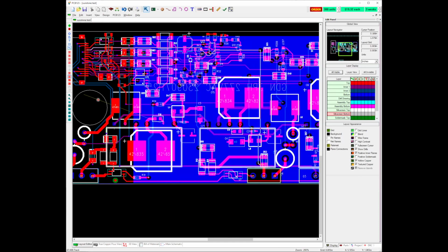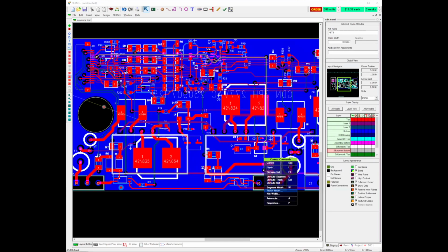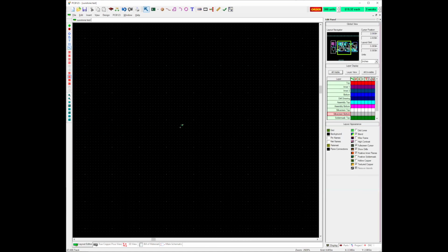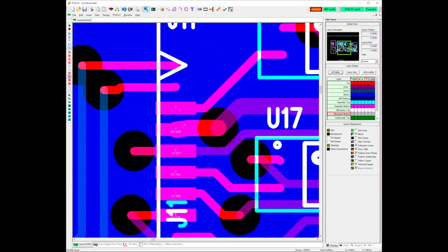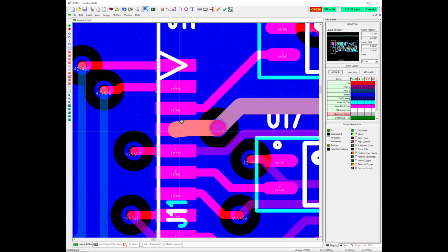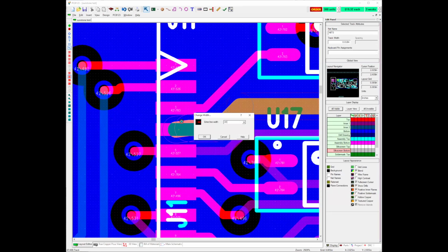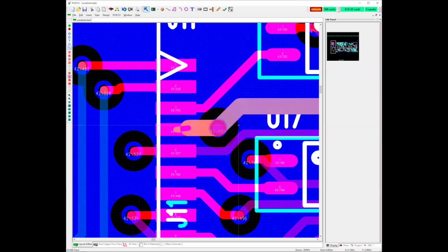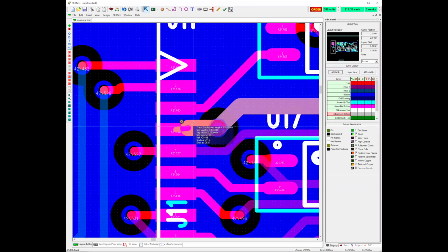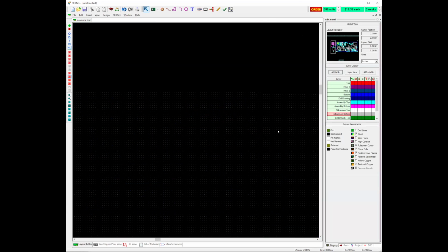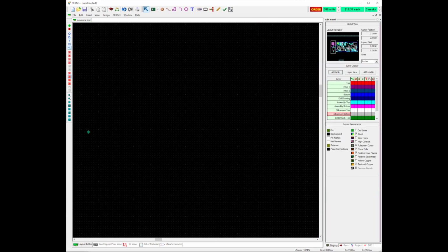It goes up here, changes it to 30 thousandths all the way across the board, but it gives me a violation here, creates an error here, which is fine. I can go back and change that, but I have to follow that whole length of the trace, and then say change this one to make the segment width 10 thousandths, and it still leaves an error because I've got an extra vertex here. So change that one. That fixes all those errors, but I still have to go back and find this other error that I created for myself